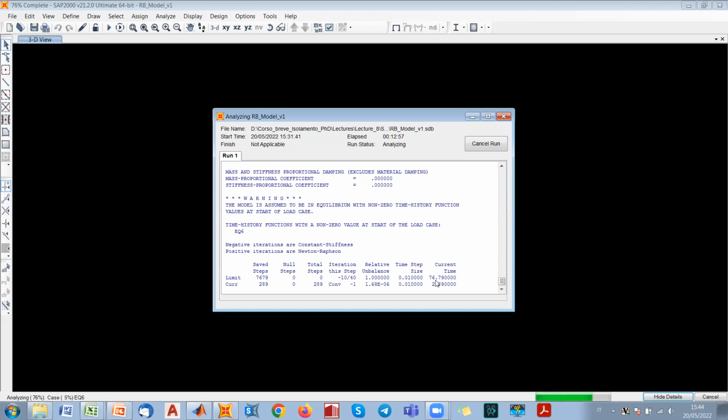So it is the same reasoning of considering the initial conditions for the building different than zero, and then to check damped and free vibrations, so without any seismic event applied at the base. But when your attention is not focused on the overall behavior of free vibrations, this is useless, because the ground motion maybe lasts, I think, 30 to 40 seconds maximum.